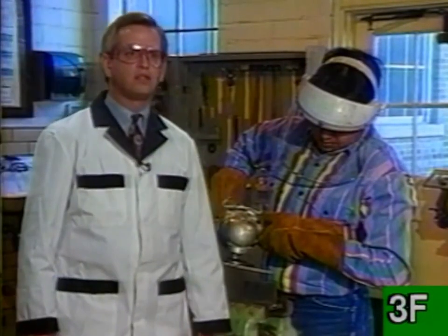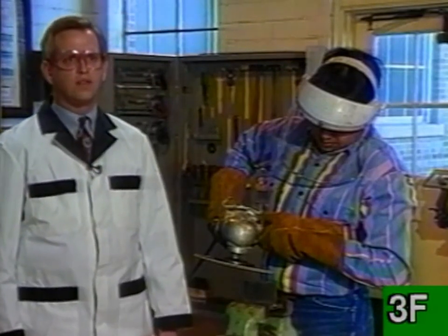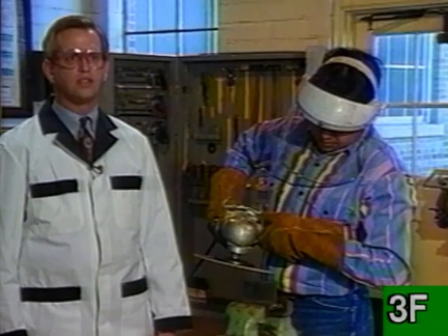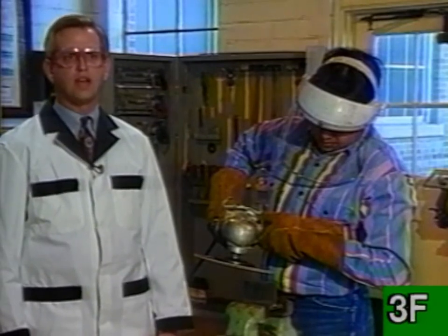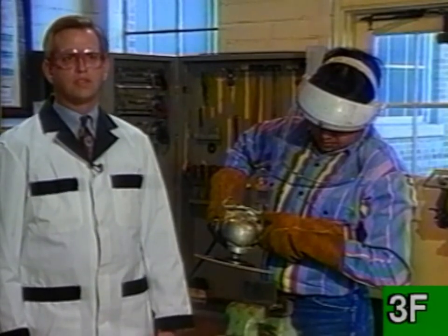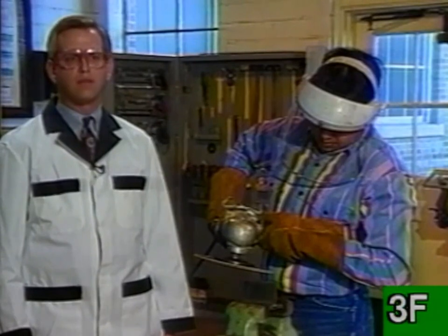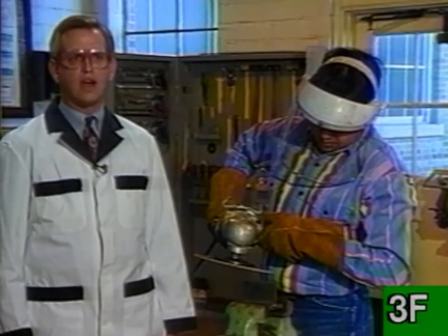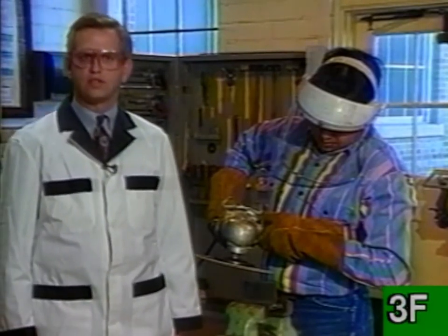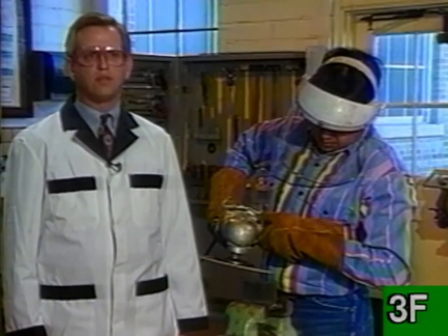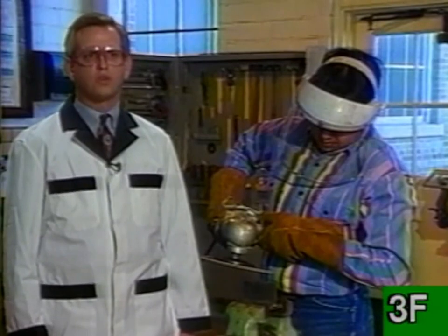This student appears to be ready to grind. However, if you'll notice, in addition to the gloves and the face shield, he should also have eye protection devices on. Safety requirements are that in addition to face shields, you also have industrial quality eyewear over your eyes, even underneath face shields. This means that he should have some Z87 approved safety spectacles or safety goggles underneath the face shield.